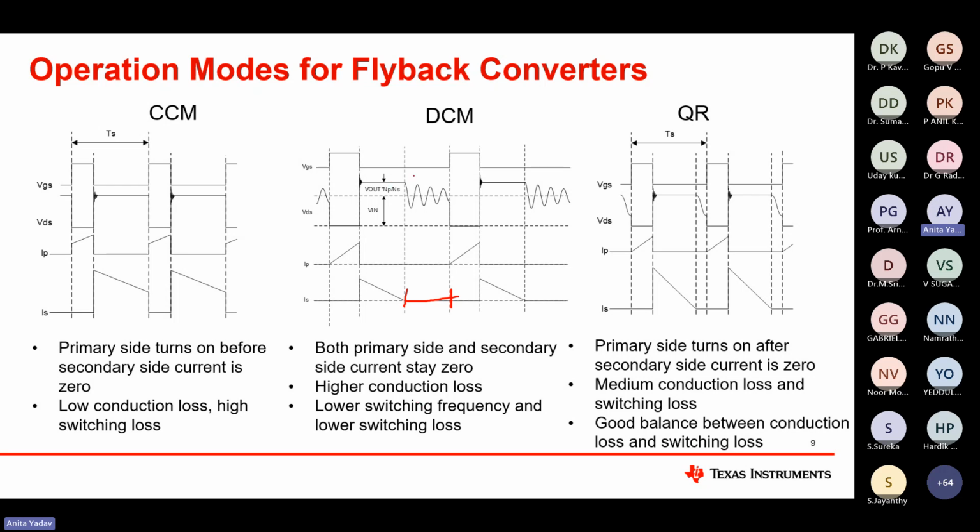Next, from the switching perspective, here is how we can identify from the waveform whether it's CCM, DCM or something else. At the edge, you will see that the current reaches zero. Another term generally used is that the transformer got demagnetized here. After that, at any number of valley, it can start switching again depending upon the control law.